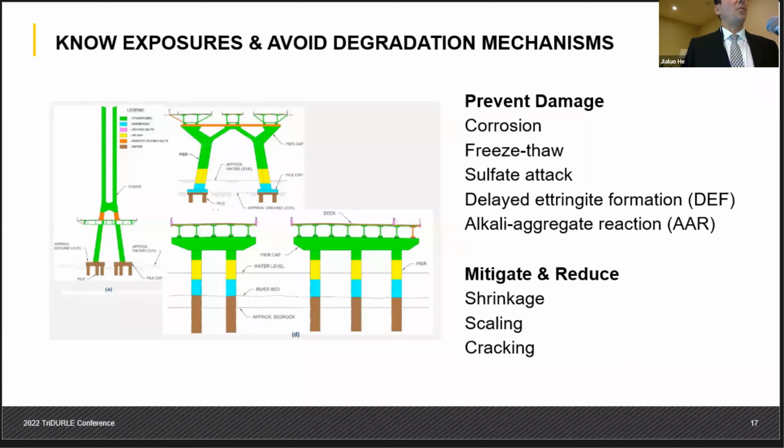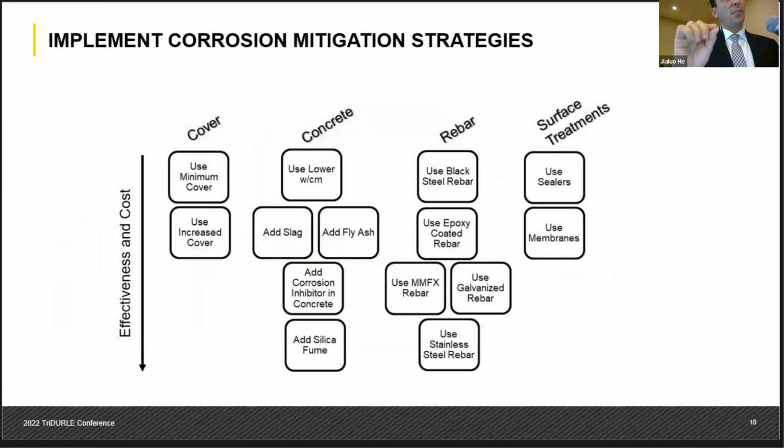How do we actually come up with a consensus-based solution where we can say, you know what, we know that it's not going to be crack-free, but what is the level of cracking we can tolerate? What are the repairs we can manage? And how can we all work together towards the right solution? It's very important that cracking, when we talk about cracking, is a client, designer, concrete contractor, concrete producer issue. It's not just a concrete producer issue. It's not just a contractor issue. It's not just a design issue. It's everybody, right? Everybody needs to be in that game.